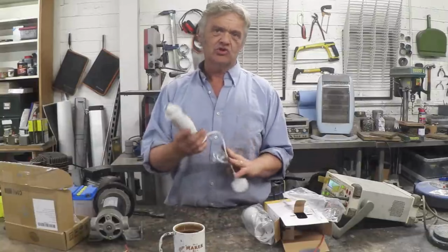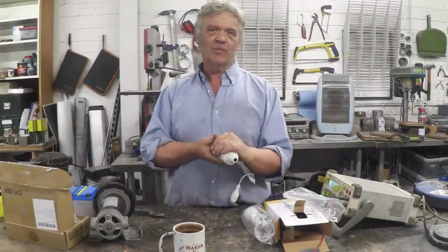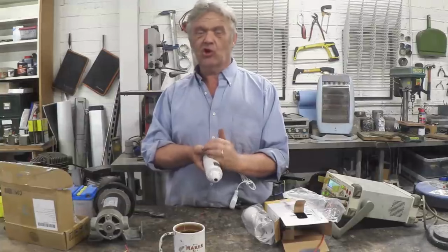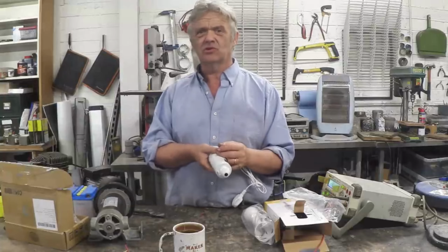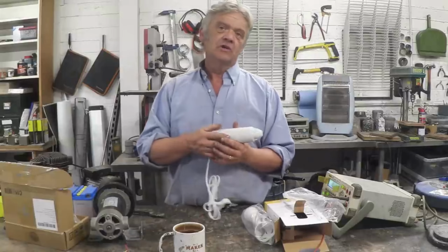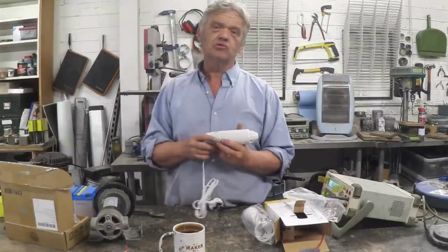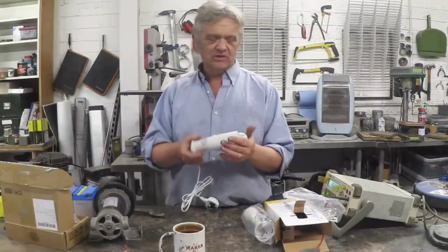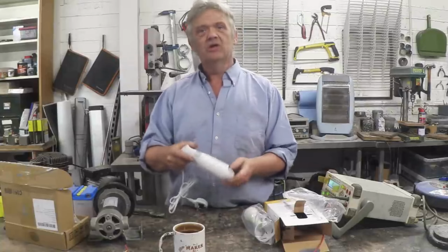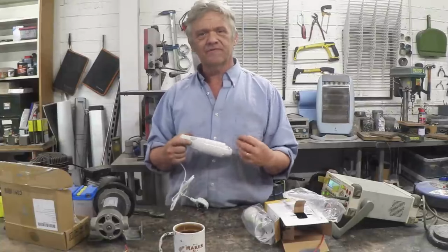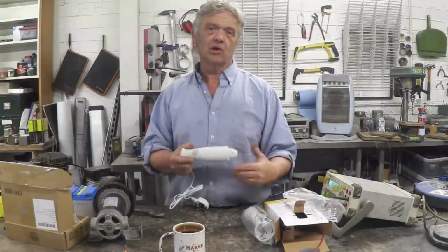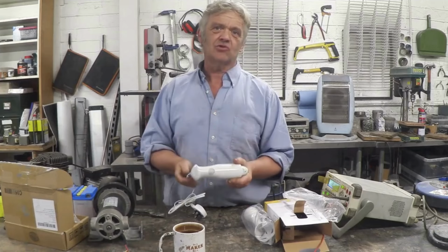But that's the blender body itself, and in there is that DC motor. Now that DC motor is a 240 volt DC motor meant to turn in the region of 8,000 to 10,000 RPM. So the RPM per volt is going to be relatively high, but they spin really easily. So it's going to be millinewton meters actually. So the millinewton meter per amp is going to be really low. You're going to be able to feel there's a lack of torque. So you can expect quite high voltages but very low torque. Anyway, let's get this motor out and have a look at it.